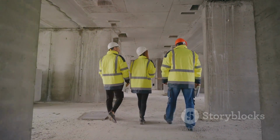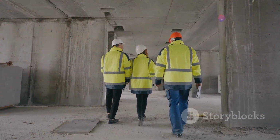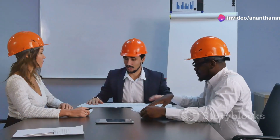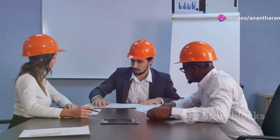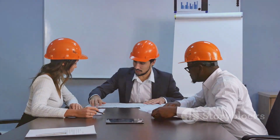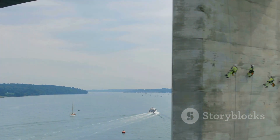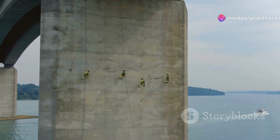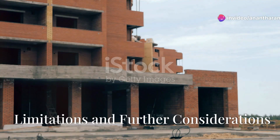This factor considers potential variations in material properties, unexpected loads, and construction tolerances. The choice of safety factor depends on the specific application and the level of risk involved. Structures with higher consequences of failure, such as bridges and aircraft, require larger safety factors.